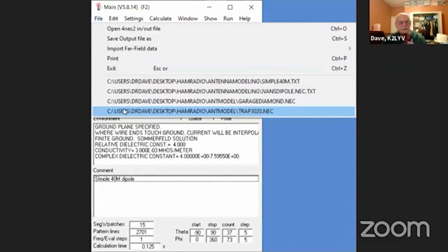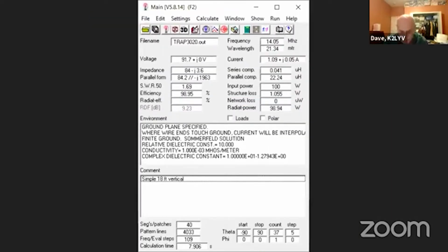Okay, so here's an antenna. This is a more complicated one. I think it was about 2 years ago I wrote an article for QEX. I may have even given a talk at one of the tech cons. The idea here was that normally, if you want to make a dipole that works on 2 bands, you put in traps so that you cut off the outside ends, so the inner part of the antenna is at the higher band and the outer part of the antenna works on the lower band.